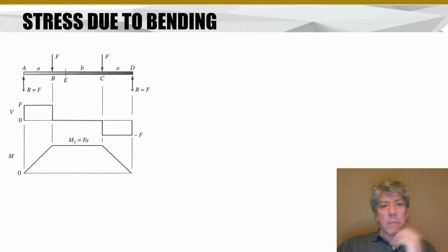Well, we've studied beams, and we know that if we set up a beam with 4-point loading like this, where the magnitude of the load and the reactions is simply F, we can write or compute a shear diagram and a moment diagram. The shear diagram is pretty simple because the reaction on the left is magnitude F, the load at position B is magnitude F, and so of course your shear diagram would go up to a magnitude of F, go over, and then drop down to 0.